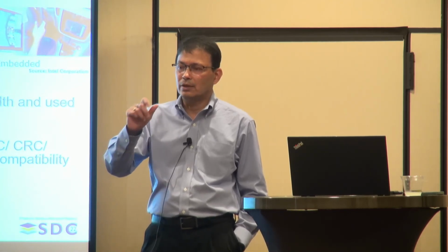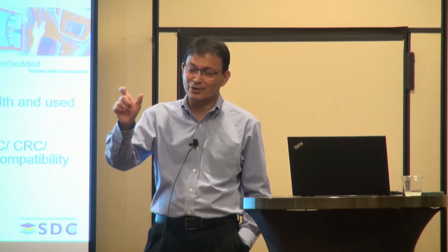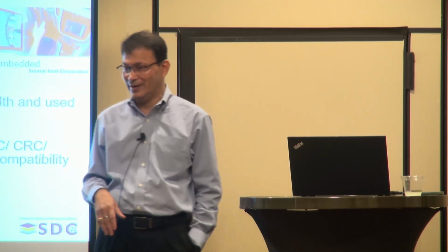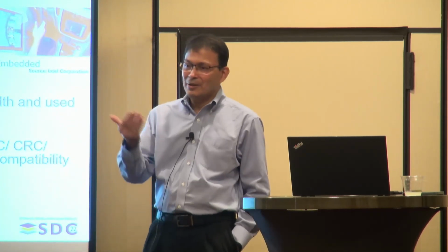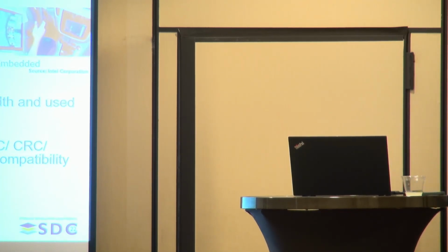Actually, reads are easy, because if I look at the reads I know there is a huge bandwidth demand coming. So I can have some intelligence to predict that. Writes might be a little bit trickier, but even with a write, I can always look at how far my hardware queues are getting backed up. Based on that, I can decide, hey, these things are coming in fast. The build-up is really fast, so instead of taking small steps, I might just decide to go all the way to by 16 and then dial it down later on. So you could have different policies depending on the slope at which things are building up, and based on that, you can make a decision.